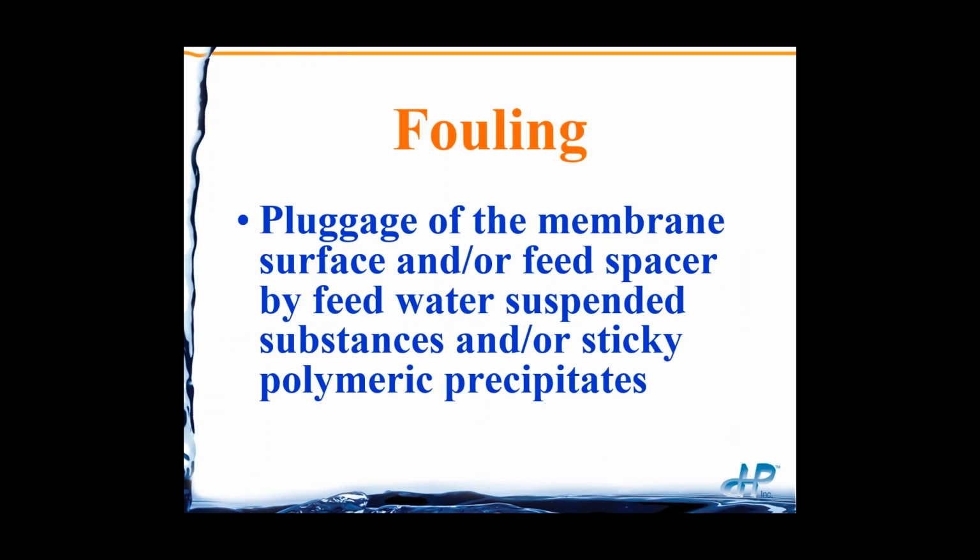Now let's take a look at fouling. So here again is our definition, not a universal standardized definition. So here for fouling, we're talking about particles, living or non-living particles. So living particles, mainly bacteria. Non-living particles can be anything from silt, sand, clay, precipitates like iron, rust, things like that. So either the particles come in and don't leave, so they don't go out in the concentrate, they get stuck somewhere,